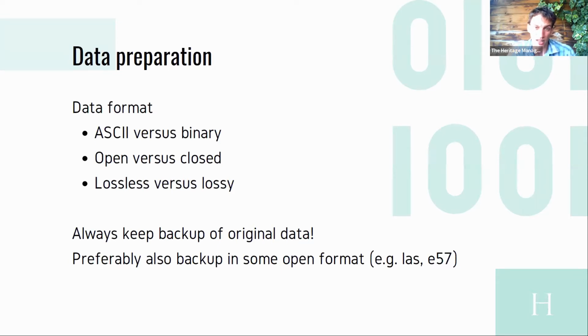It's obviously not recommended, but if you open it, you will just have a file with, line per line, the coordinates of that point accompanied with the intensity values and/or the RGB value. So it's all human readable, and that's an advantage. And if you are a programmer, it's very easy to program your own applications on top of that. The big disadvantage is that it can get very voluminous. The amount of space required to save your ASCII data, especially with large point clouds, is very large.